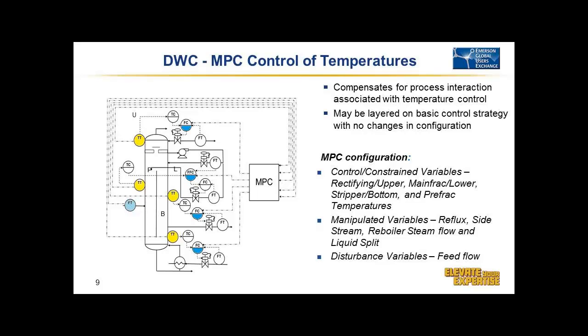And we're doing temperature control instead of composition control. Our dividing wall column is outfitted with 24 RTDs that are hooked up to the 848s. So just by having this wireless capability, we're able to have a wide range of temperatures to select to be controlled off of. Without this wireless technology, I think we would still be running wires in our pilot column.